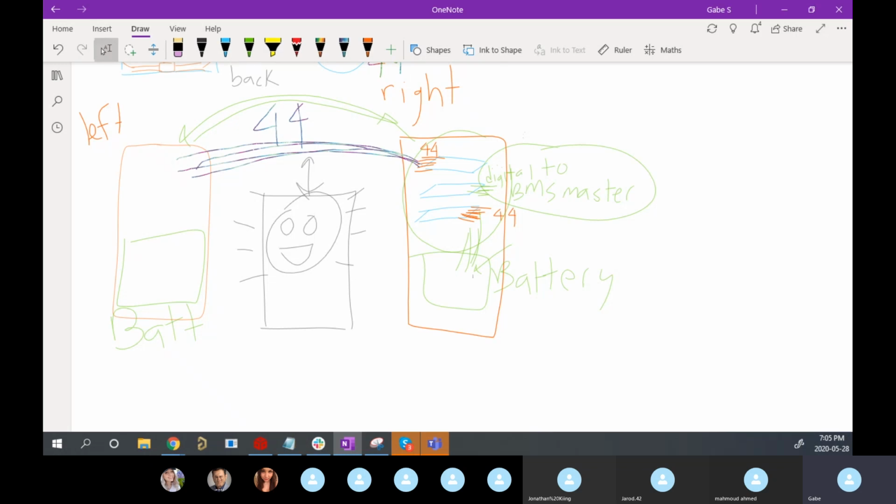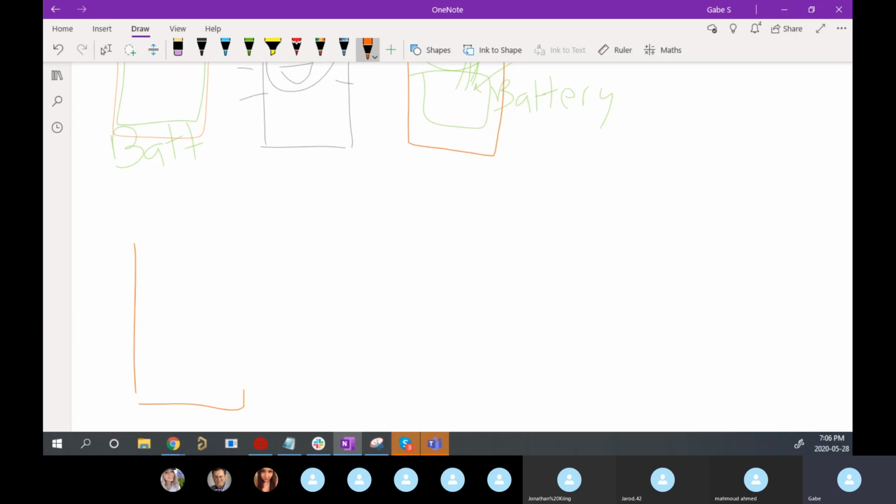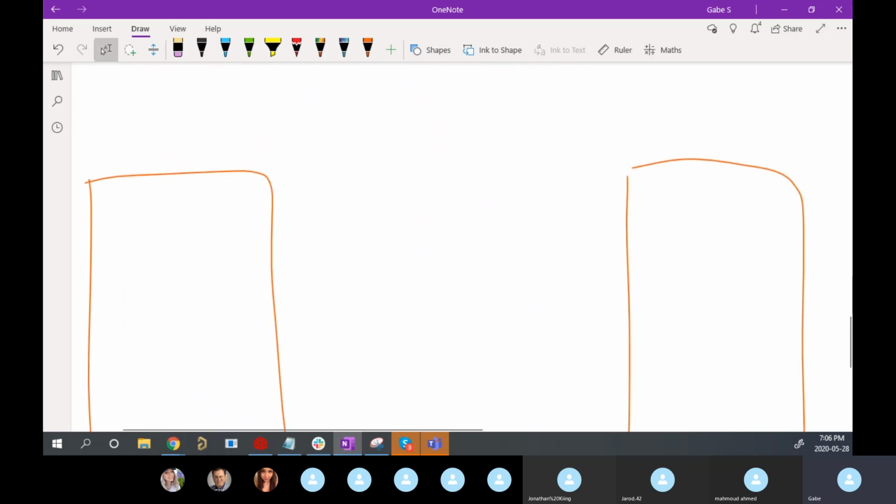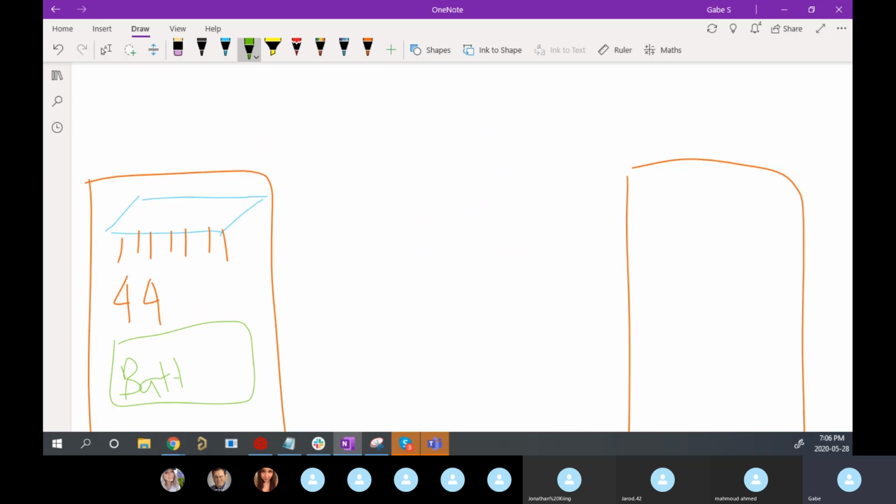And so what we kind of decided, as sort of like best of both worlds, kind of a compromise, right, is to put one in each. So here's the top board, 44, go next to our battery. Right. Send 6 analog over. Remember, 6 muxes, right? They're 8 to 1, so 1 signal comes out of each of them. Send 6 over.